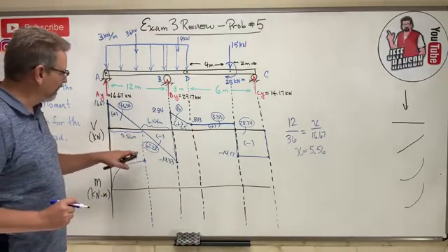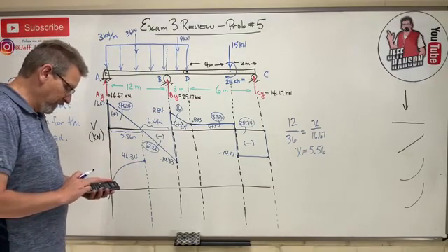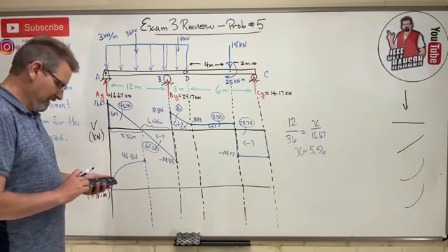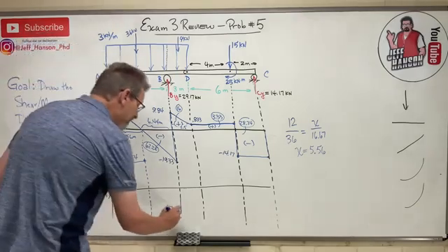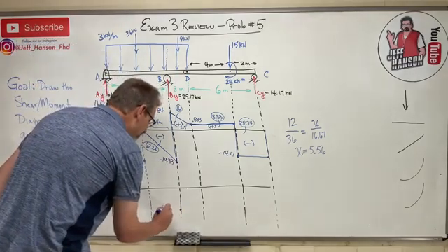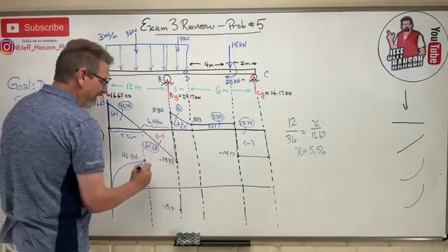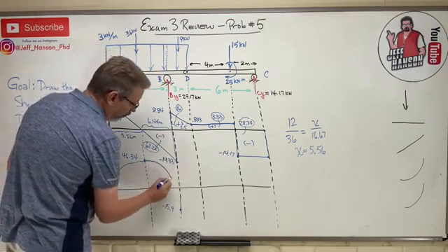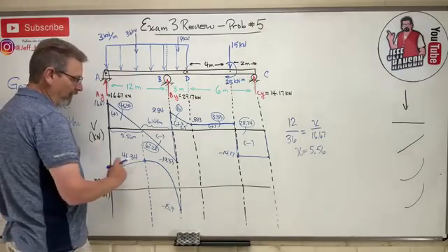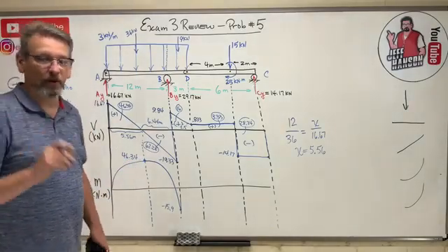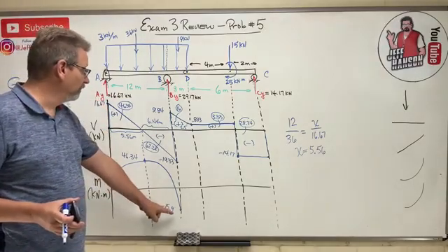Now the next section, I've got to go down 62.24, but I'm at 46.34, so 46.34 minus 62.24 equals negative 15.9. So that takes me down to right there, negative 15.9. And how do I get there? Slow, then fast. So kind of almost flat and then whoop. The inflection of these curves, this way versus that way, is probably the most missed thing. So remember the slow to fast, fast and slow trick. It's very good. Okay, so here we are.